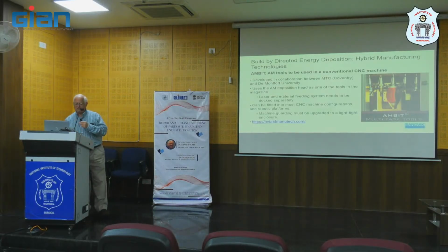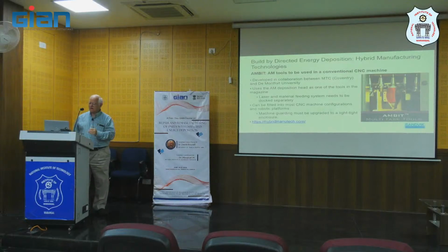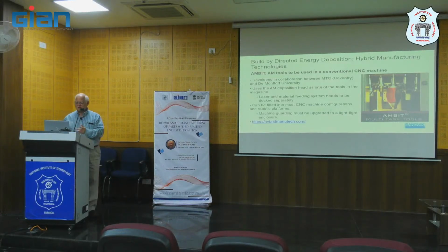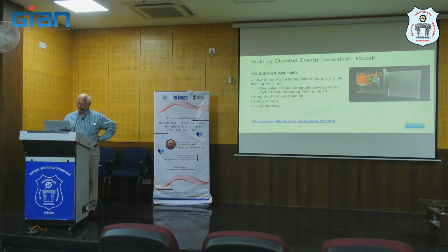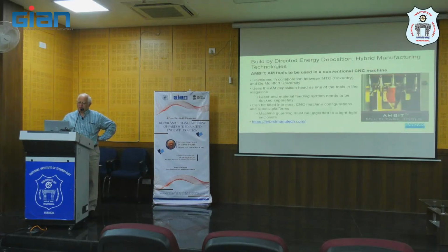It was developed at De Montfort and MTC in the United Kingdom, and it uses this AM deposition head as one of the tools in the magazine. The laser and the material feeding system need to be docked separately, and again, it can be fitted into most CNC machine configurations and robotic platforms. Then, like I mentioned, the machine guarding must be upgraded to a light-tight enclosure.